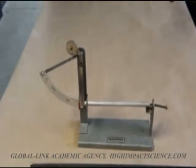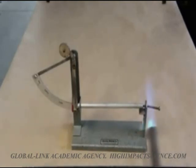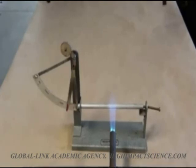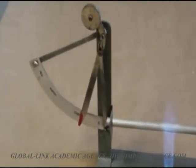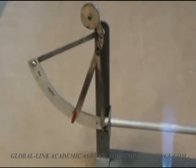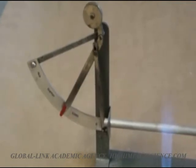The aluminium sample will be heated to show the thermal expansion. And you can already see the deflection of the needle as the aluminium increases in length due to expansion. You can use this setup to measure and compare the expansion of various materials. Just make sure you use equal lengths of the samples.